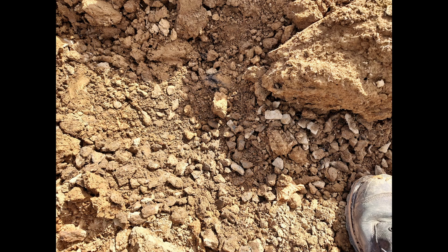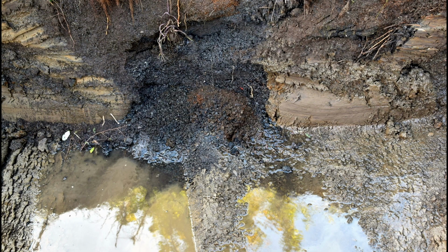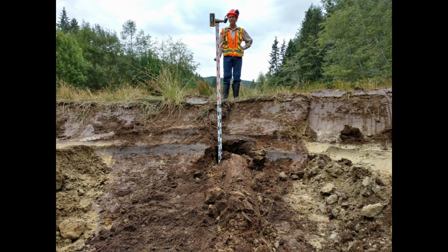Here is where a core trench has interrupted a buried drainage structure that was made from rock. This is a rock drain that was made with gravel. It measured exactly 12 by 12 inches, and we exposed it while we were building the groundwater dam. Miranda Cross is standing over a still functioning wood drain that we exposed while building a groundwater dam on Cortes Island in British Columbia, Canada.